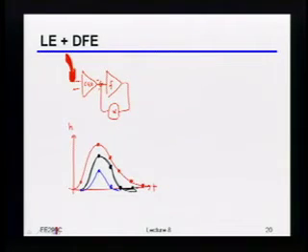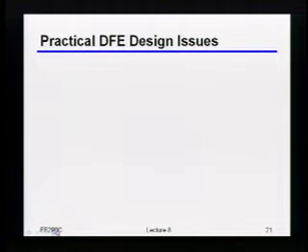Okay, so unless there are more questions on this, the next thing I just wanted to briefly mention is, we talked a bit, in the context of the receive FIR filters, about how sometimes you end up wanting to interleave those things. Turns out if you're operating at pretty high bit rates, sometimes you end up wanting to interleave the comparators as well, just because it gives you more time to either make the decision, or to actually resettle the comparator after making the decision, meaning to precharge back to the nominal state.